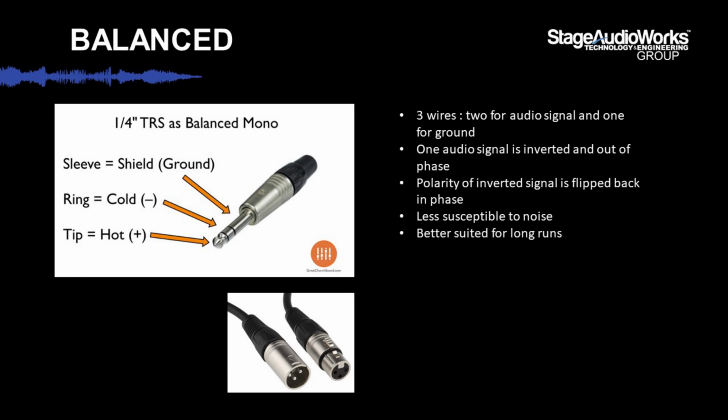About stereo versus mono, this is where we cross over from professional audio to consumer equipment. In professional audio, this type of TRS connector that you see is used for carrying a mono signal. But with consumers, you have a 3rd type of device that's using a big TRS jack like this, which is a headphone. As you may know, a headphone is generally stereo because you have 2 ears. So to keep this on a single cable, the headphone people decided to use this kind of connector.